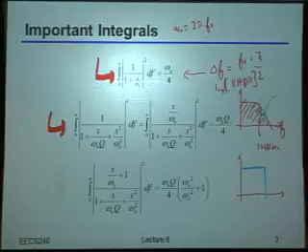Okay? Another quick shortcut that I want to point out is that for this generic second order system, and notice here, in these particular cases, I'm giving you either something with no zeros or a zero exactly at 0. They both turn out to integrate to this omega naught Q over 4 in terms of the net bandwidth.